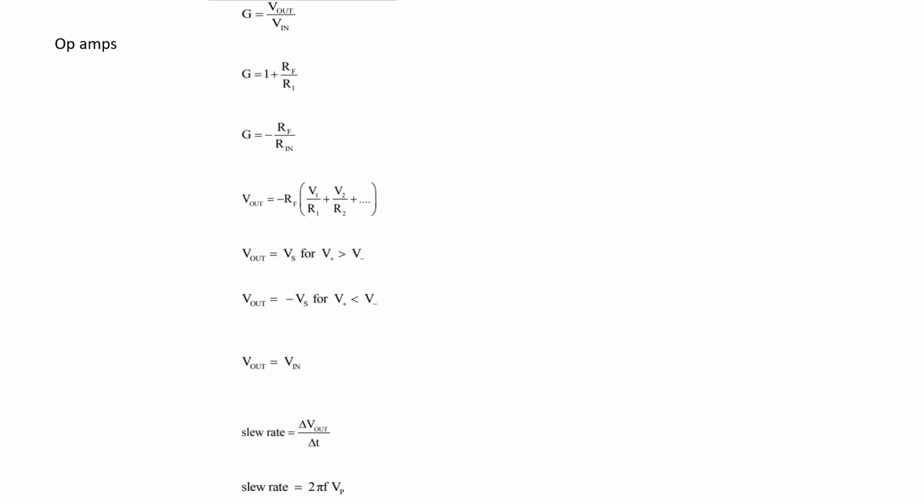These 2, this is obviously a non-inverting, this is an inverting. I'm sure you guys all know now. Resistors don't go to the plus sign, do they? Yeah, so you know how to draw those now, don't you? If it's non-inverting there, then obviously that would be V in, that would be 0 volts, just so you know, that would be a non-inverting one there. Okay, I'm not going to draw the other one.